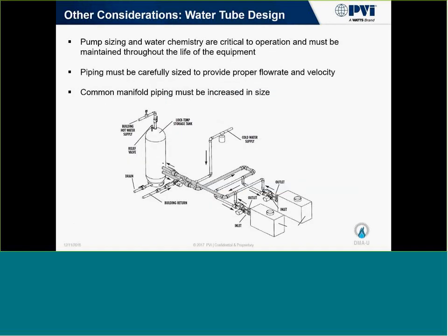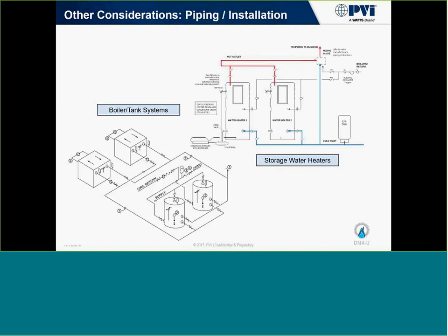So as we said before, it's very important to have everything in line for a boiler tank design. Everything has to work together. It's more complicated. There's a lot more standby loss because of the piping, which they cannot take into consideration for their efficiency equations. So here's the difference between those piping diagrams. Top right, tank design, bottom left, boiler tank design, and there's also a lot of additional installation costs that would be accrued because of that.